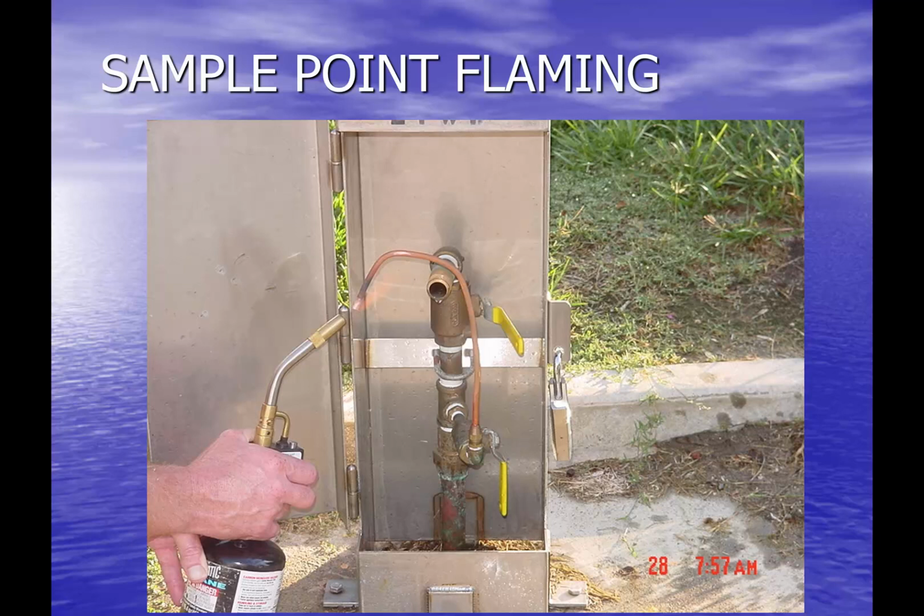It helps to ensure, and the whole point of doing it is to help ensure, that we don't have false positives, that we don't have a sample that comes back as positive purely because there was something funky going on with the sample line, as opposed to a problem with the distribution system water itself. So for us, it takes a few seconds to do it. It's belt and suspenders perhaps, but we are trying to avoid having any positives of any kind, false or otherwise.